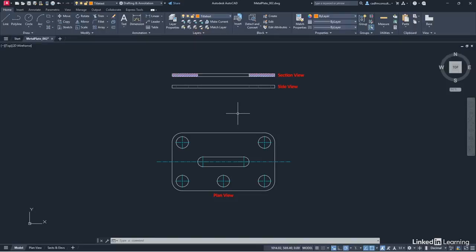Now, text styles we've done, and we've placed some single line text and some multi-line text. Pretty basic what we've done, but you can see how that workflow works now, and you can now go away and, little call to action for you, experiment with that multi-line text and single line text. Now, what we're going to do now is create a dimension style in the same way we created a text style. We're going to set a bunch of preset settings so that our dimension annotation appears in the drawing the way we want it to.